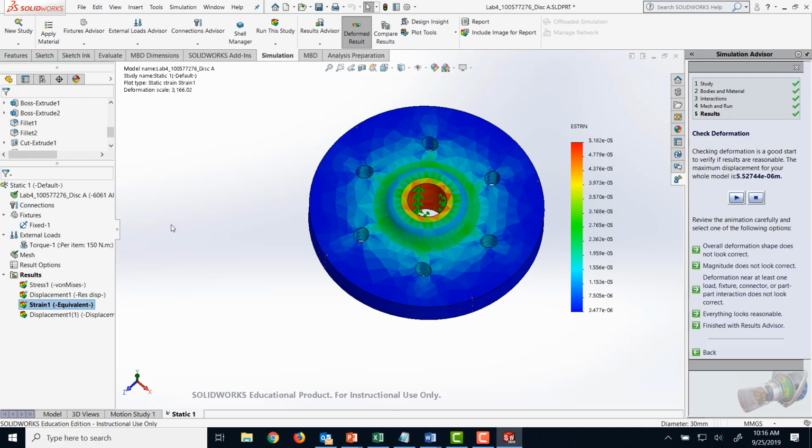In your lab manual, the next step asks you to refine your mesh and make it a smaller mesh. Whenever you're doing finite element analysis, there are two studies that you always have to do. First of all, you need to validate your numerical model that you're trying to solve a physical problem with. Second, you need a grid density study, where you change the mesh sizes until the results don't change beyond some acceptable level, which you define.